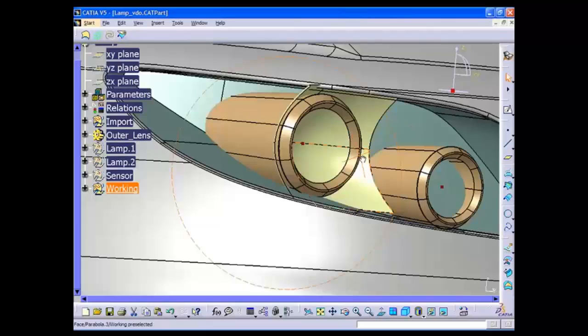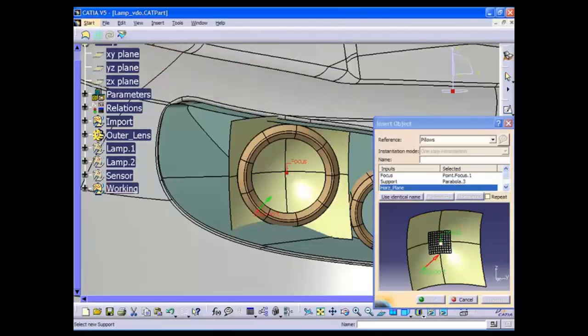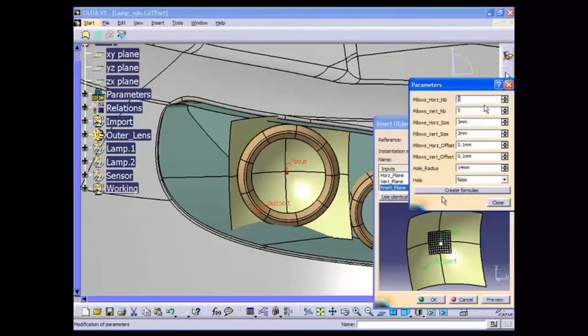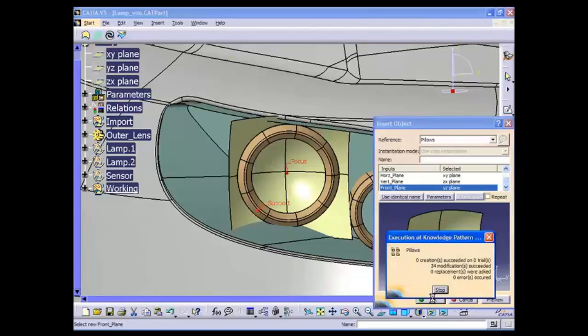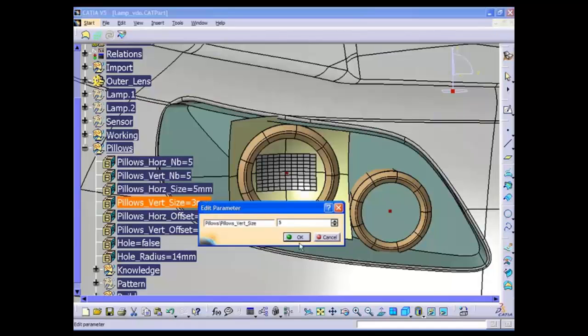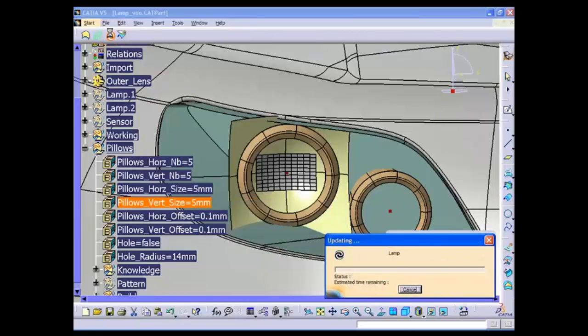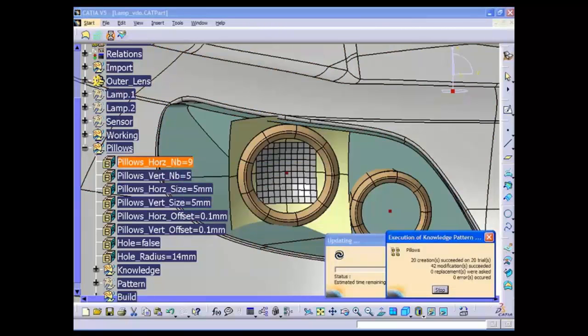Characteristics such as size and position are under user control thanks to parameters. So the designer makes some modifications to the size of the surface and the focal length. The designer then inserts another template to instantiate a geometrical pattern of reflector elements onto the parabolic surface. The pattern is comprised of a great number of reflector elements and is morphed onto the support surface and created in a matter of seconds.